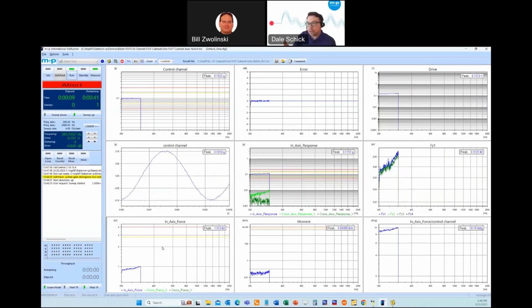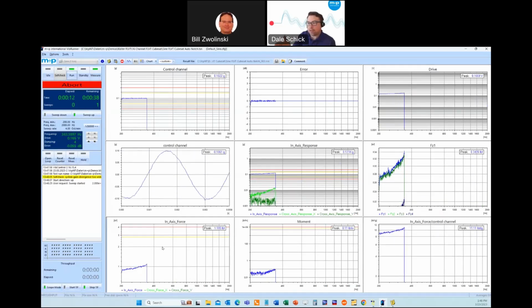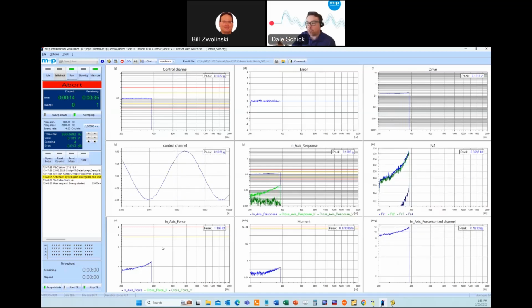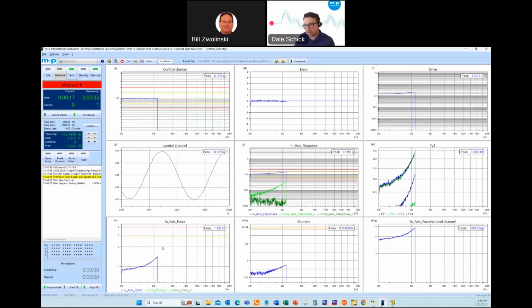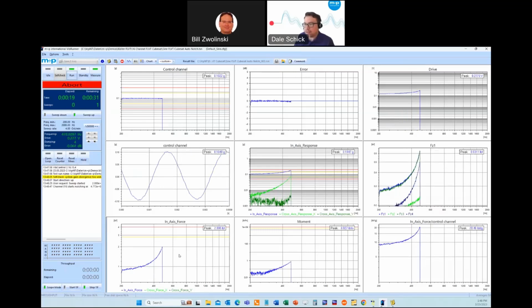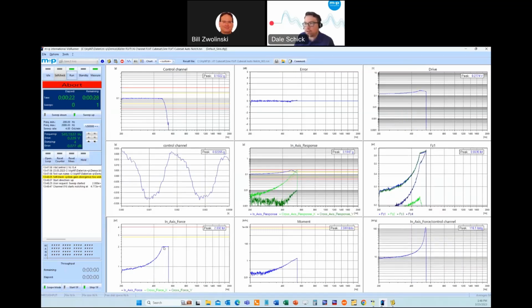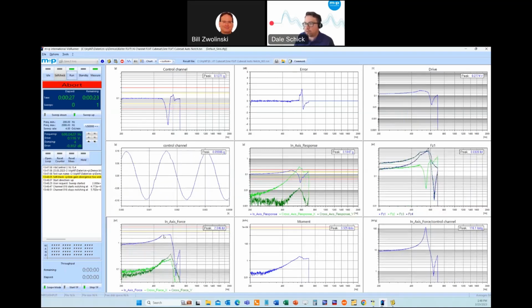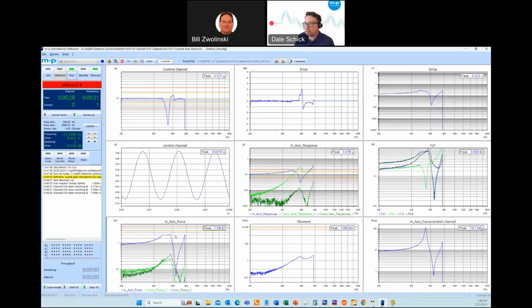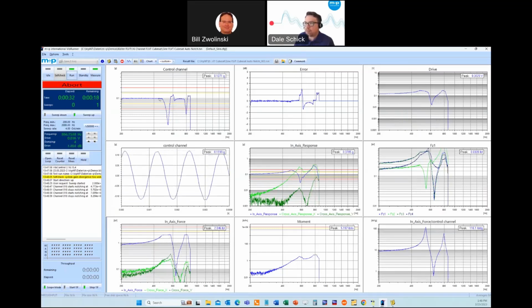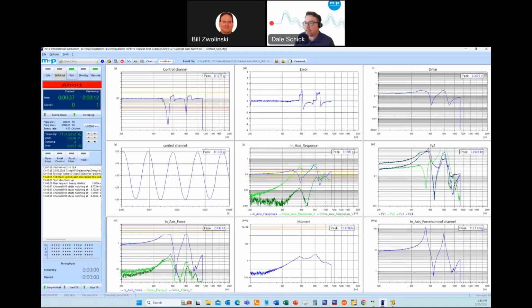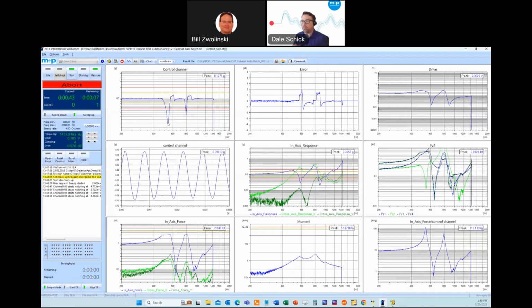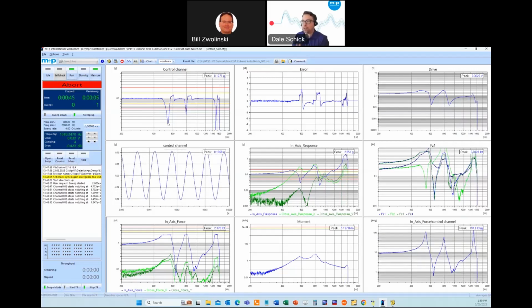By the way, this could be cross-axis response. It could be in-axis force combined with moment, combined with some responses on the test article. And the lesson there is that whichever one takes the most error is the one which will take control. Now you can see our first mode, we've kind of cut off the mountain, so to speak, of force input, and we have a very particularly shaped notch, which is exactly what the test article calls for. This is basically slowing the inertia of the input force in order to give you a perfect test profile.